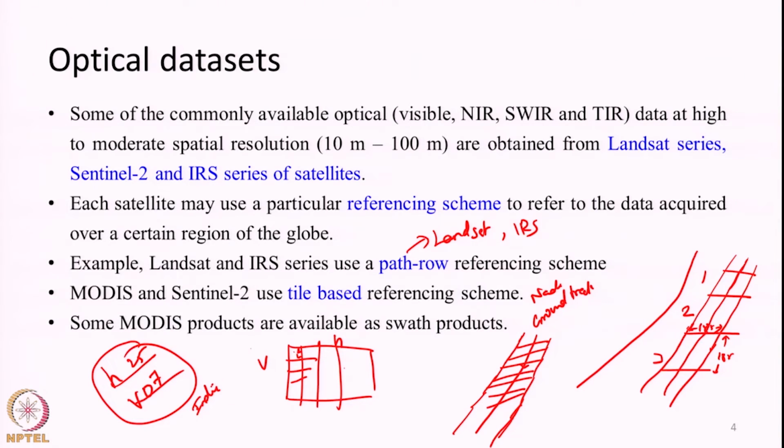As the MODIS sensor has a very wide scanning angle, the same point on the globe can be covered from different orbits, right. So, from whatever orbit the ground point is covered, the data will be processed and populated onto this grid. So, we will not know from which orbit or scan angle it was imaged. The information will be there, but we have to dig deeper into the metadata. The swath information will be removed, and everything will be converted into this kind of grid.